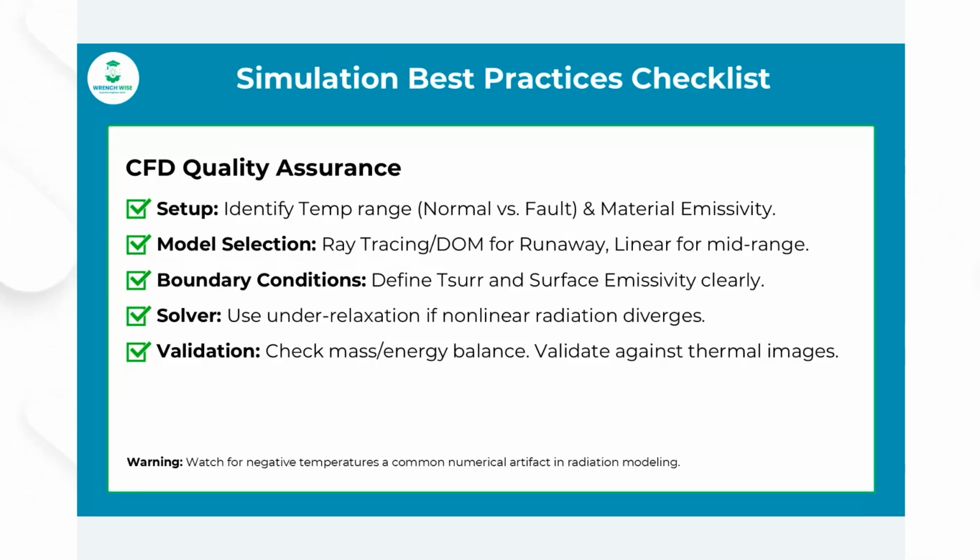Similarly, for a very simple case where you're trying to run a battery failure model with convection on top of it, you could also monitor the outlet temperature of your fluid itself to understand if the outlet temperature is correct or not. Ultimately, you want to compare your CFD contours against experimental or thermal camera footage at least.